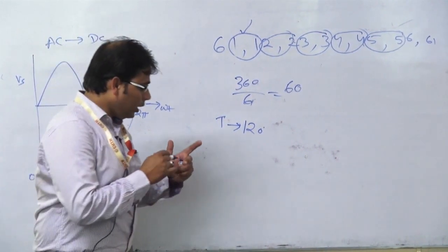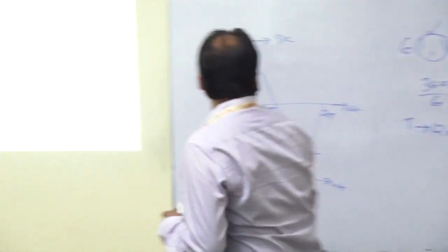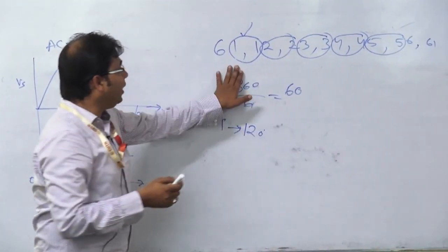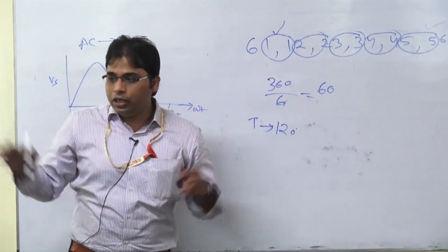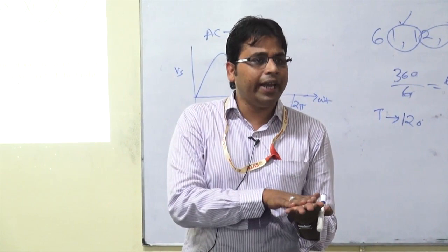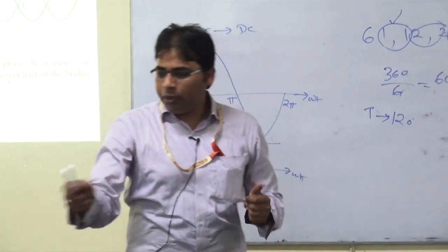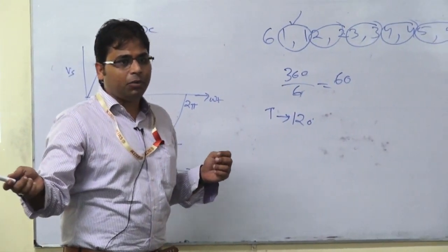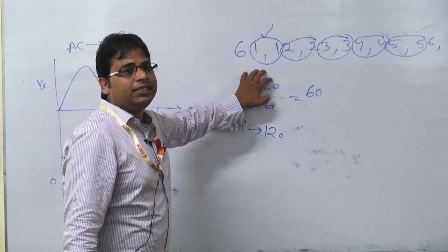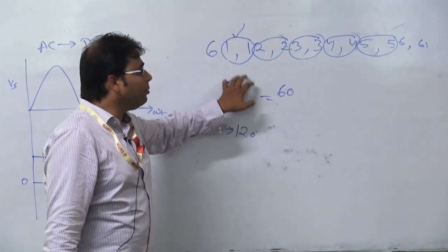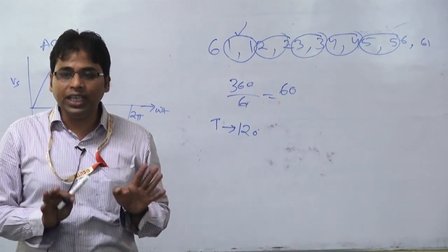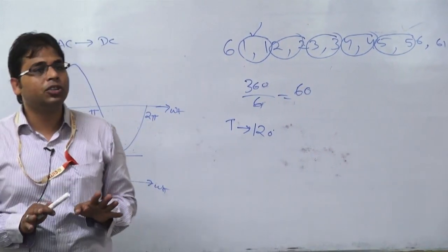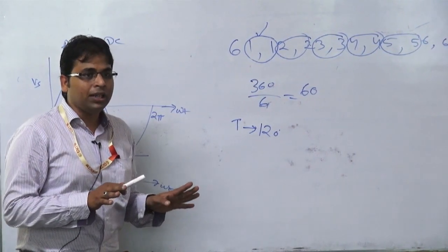Okay. Now, this is the conduction sequence, how it came. We have already discussed here the more positive and more negative phases. Because of the more positive and more negative phases, this conduction sequence came. This is nothing but the natural crossover of the 3-phase source voltage waveform.